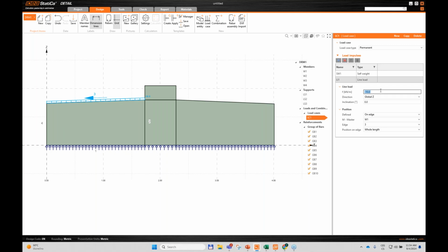So I will use line nodes for all the inputs. And because it's not the same, this one is for the moment that I was able to calculate easily from the stresses, and I just transfer it to the line load. And because it's not the same on both sides, it will create a moment.